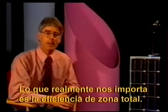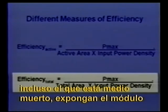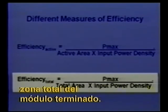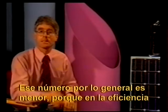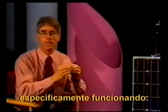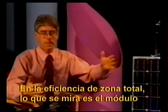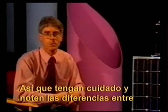What we really care about is total area efficiency. Take into account all the space that's being used, even the stuff that's kind of dead. Shine light on the module and measure the electrical output, and divide that output by the total area of the finished module. That's what we call total area efficiency. That number is usually less, because in active area efficiency, you're only looking at the particular part of the cell that's working. In total area efficiency, you're looking at the total module, and there's more area taken up by dead space. So be careful and notice the differences between those two if you hear any announcements.